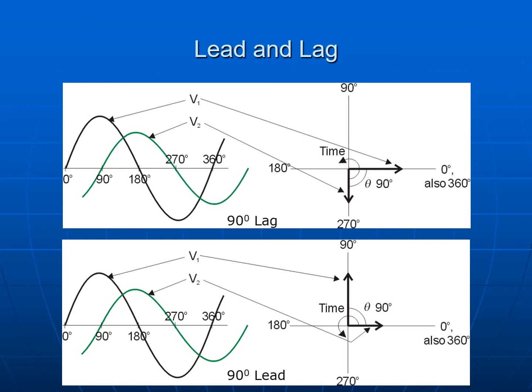On the second page, we also have the exact same phasors on our sine wave diagram. However, when we look at our phasor diagram, you'll see that we changed the reference. Now my reference is V2. So now I can say that V1 leads V2. So whether something is lagging or leading all depends on what we're using as a reference. In our circuitry, normally we're going to use whatever's our constant. So in a series circuit, we're going to use our current as our reference. Therefore, we're going to show our voltage as a leading or lagging value towards our current. That would tell us where our voltage should go on our phasor diagrams.